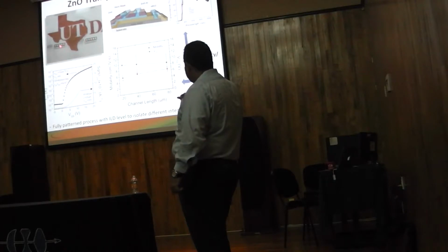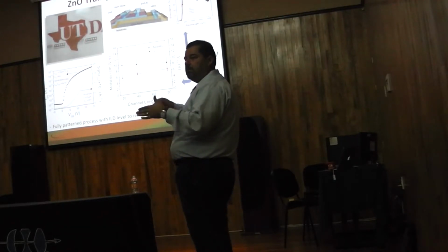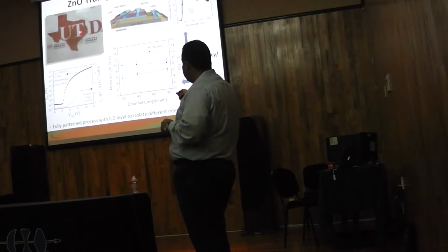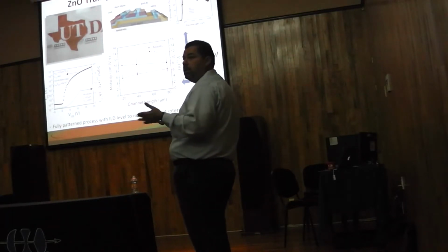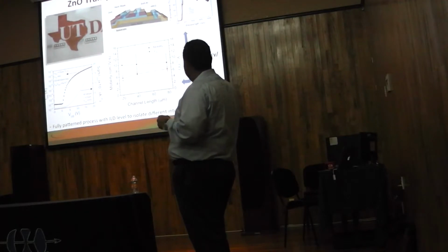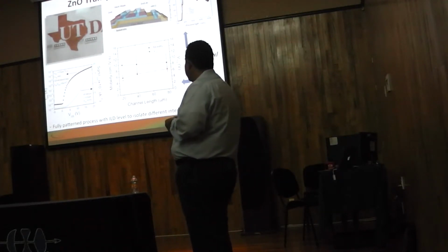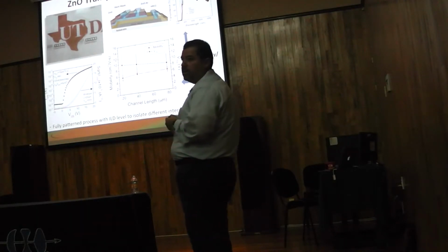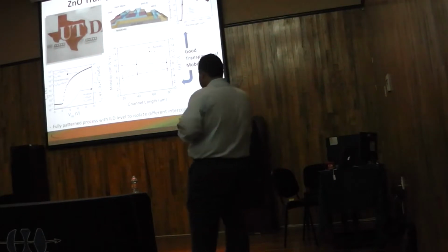This that you see there are what we call alignment marks. When we need to make many masks, we need to align them. So the fact that you don't see the devices means that they are fully transparent, this is great. And just to make sure, we did the transmittance measurements. So we have about 80% or so transmittance with mobilities in the order of 10 or so centimeters squared per volt second, which is really cool.